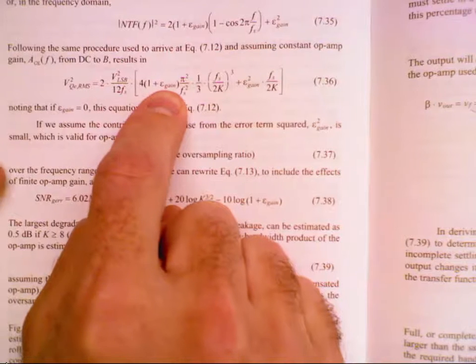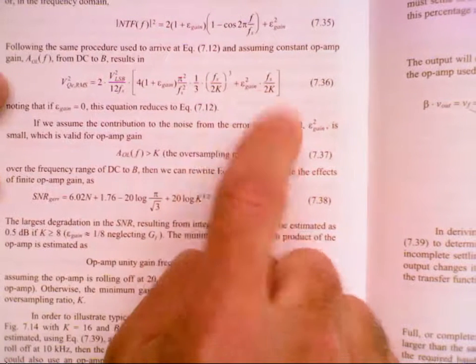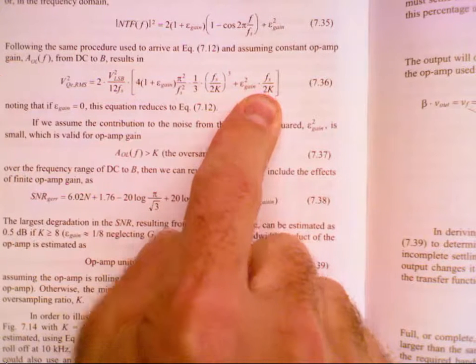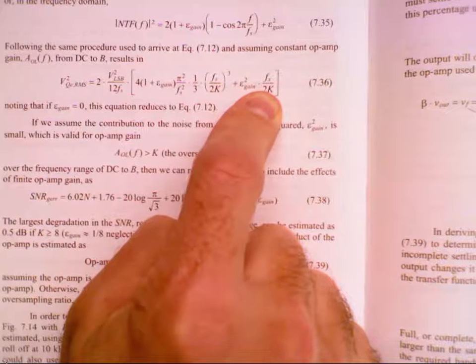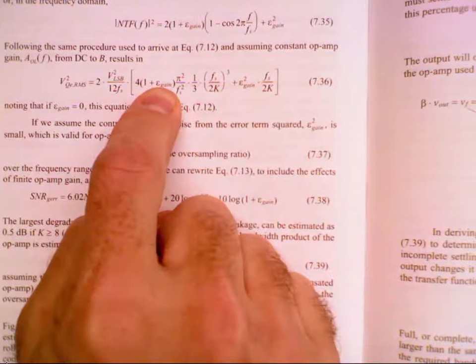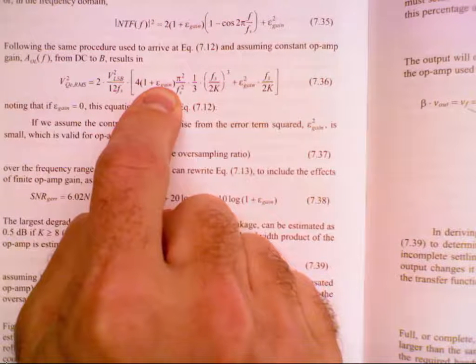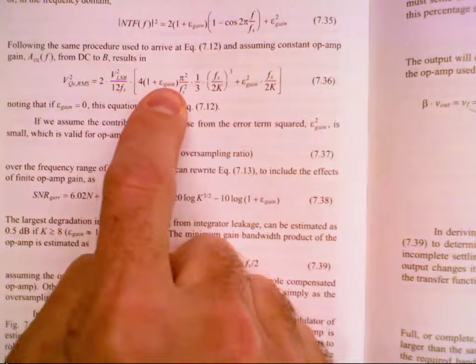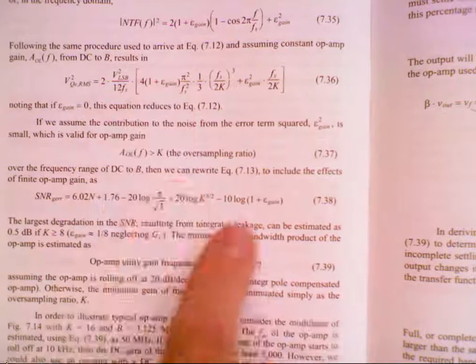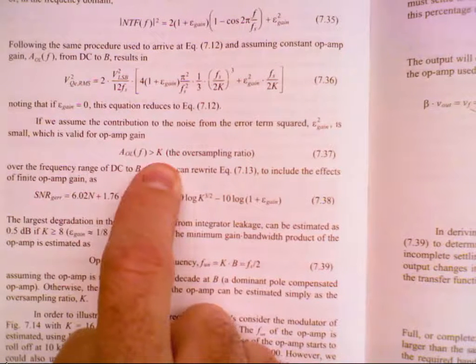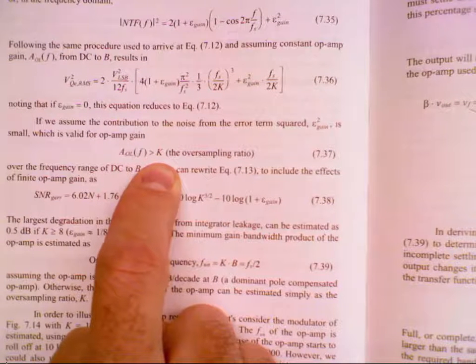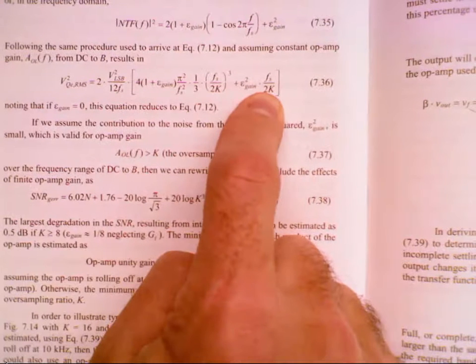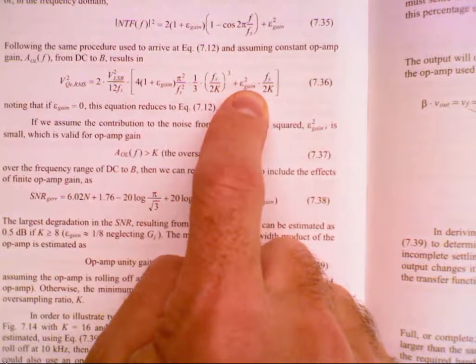And so what I said here is, okay, if we assume this term is small, 0.01 squared is 0.0001, then this term dominates, and in a practical case it is. And you ask, okay, well, if I look at this, how big does the open loop gain have to be? Remembering that CI over CF times 1 over AOL. If you look at that, if you put it in here for this term right here, I'm skipping too much. Let me back up and write it.